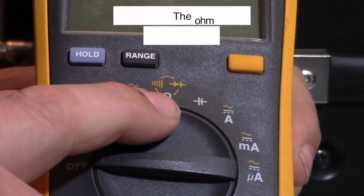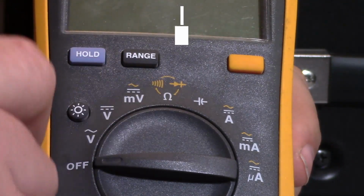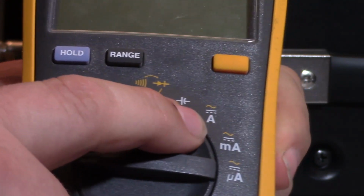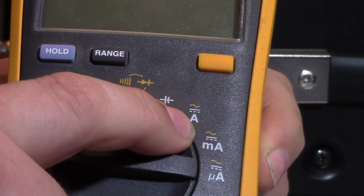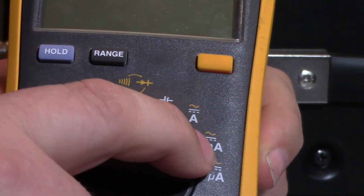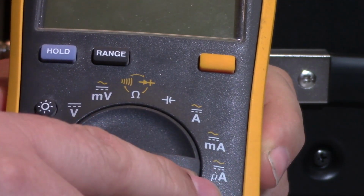Then you have ohms, and above that you have a continuity check, which will beep a sound, and then you have a diode check. It'll actually show you the forward voltage drop on it. You have capacitance, amps DC and amps AC. Amps AC requires a special probe. You have milliamps AC and DC, and then you have microamps AC and DC.